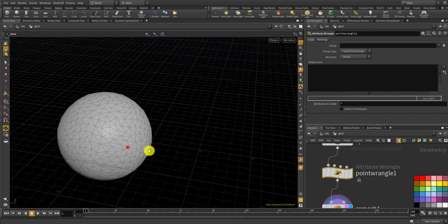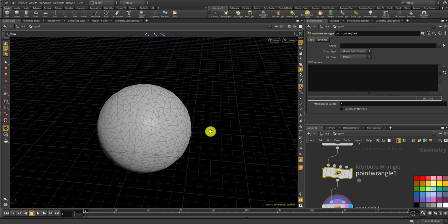Okay, and for testing, let's just use the x coordinates to use it for a target mesh size. So let's get the float x as point x, and I'm gonna set the target mesh size attribute for the point to be fit x from -1 to 1 to, let's say, 0.5 to 3.0. Okay.